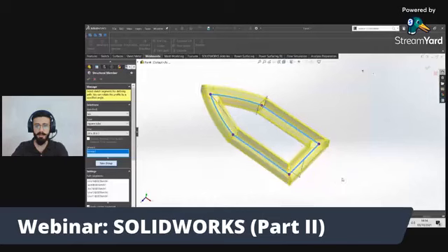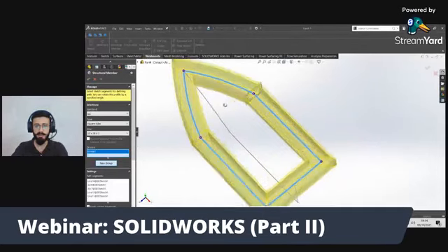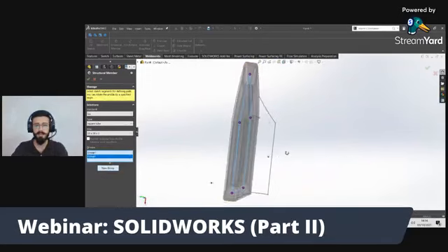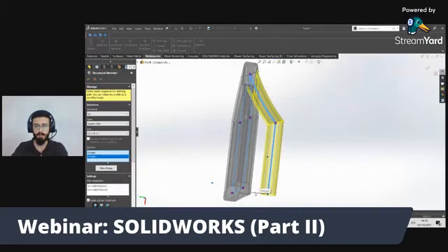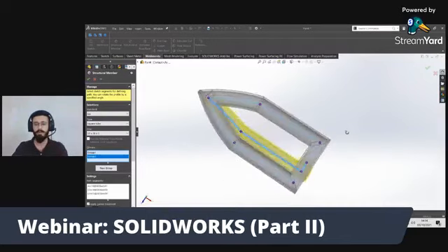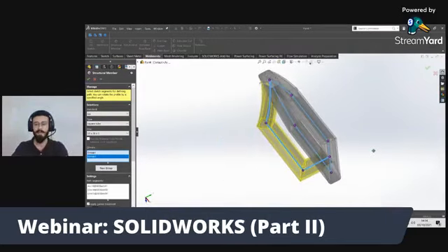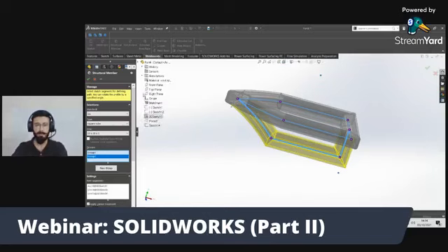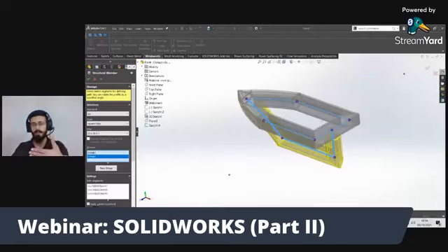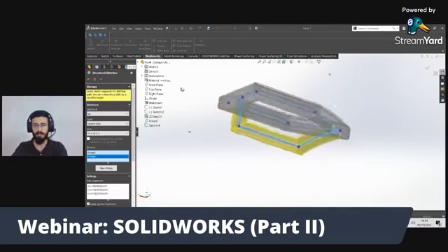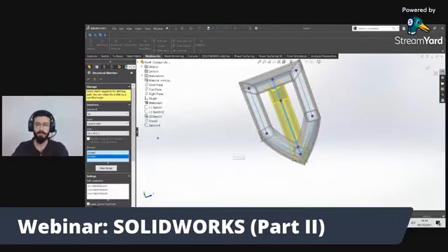this is our one plane. There is a bit of difference here. It seems a bit cleaner if we use a 3D sketch. Then again group 2, and for every plane there should be a new group, because the plane is changed. The upper body is designed in the top plane, and the lower body is designed in our front plane. So that's why we have to use different groups for weldments.